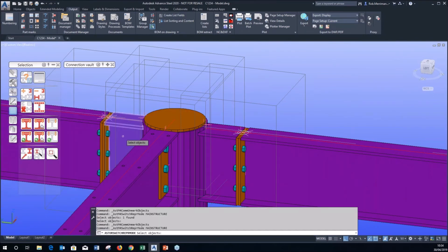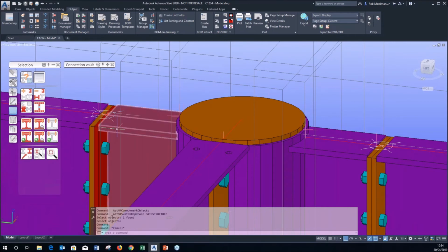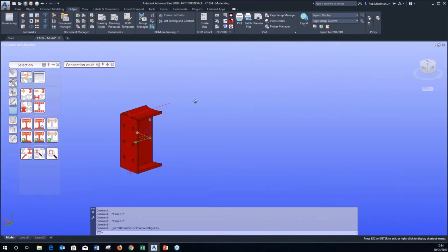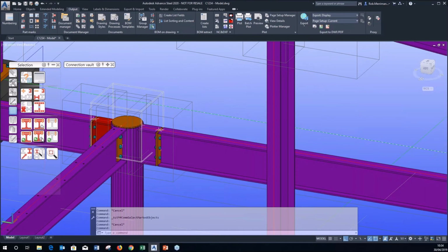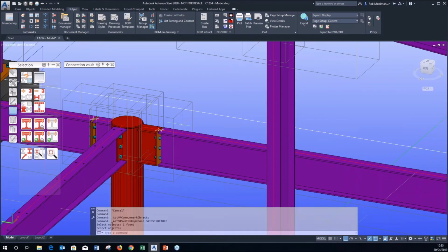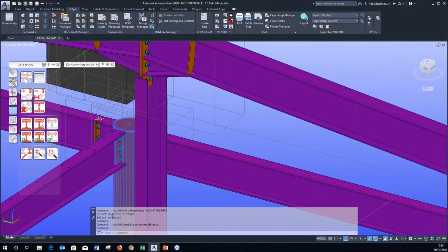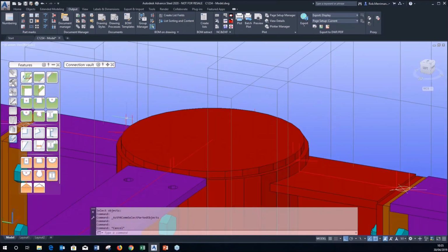Now if I do a shop attached on this, what it's actually doing is, because the end-to-end splice will automatically weld this plate to this I-beam, that would go out as one assembly. So that there would go out as one assembly. So it would get maybe galvanized, maybe powder coated. Hopefully your workshop might pick up on it, but if one person was making some bits and one person making other bits, they might assume that's what you've wanted to do. And then that would go out as one assembly, because I've used a feature to attach the items in here.